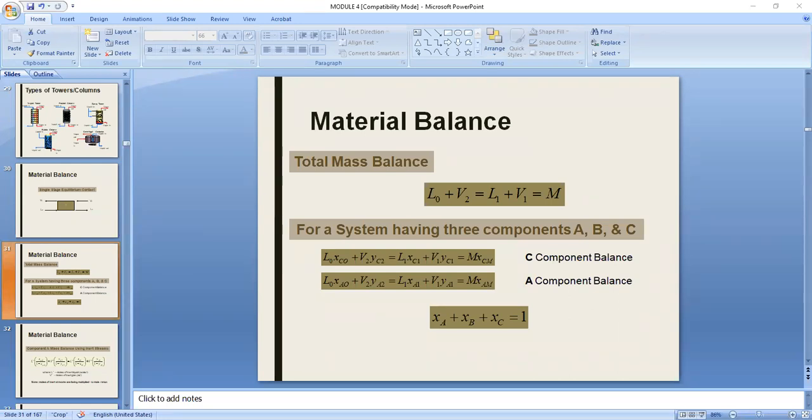So we need to specify the component on which a particular mole fraction is based, and at the same time identify where it comes from. If it's coming from stage 1 or plate 1, that is why you have two subscripts for X and Y: one for the component used as a basis and one for the plate or stage where it came from.